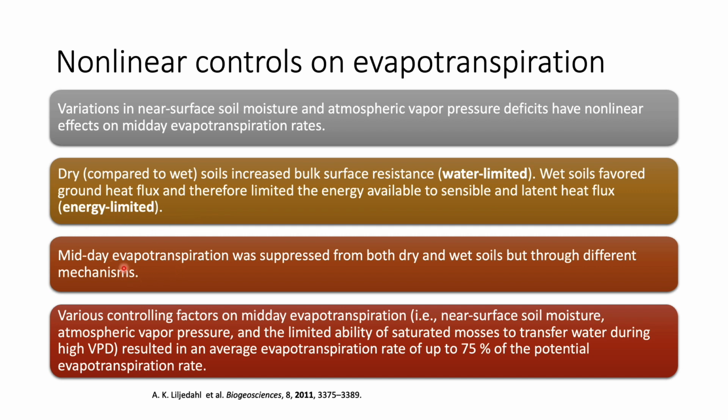And here the midday evapotranspiration was suppressed in both the dry and wet soil, but through different mechanisms. So they both affect it, but through different mechanisms. Then various controlling factors at the midday evapotranspiration are given here. So we have to account for all these things when we do the calculation for evapotranspiration.